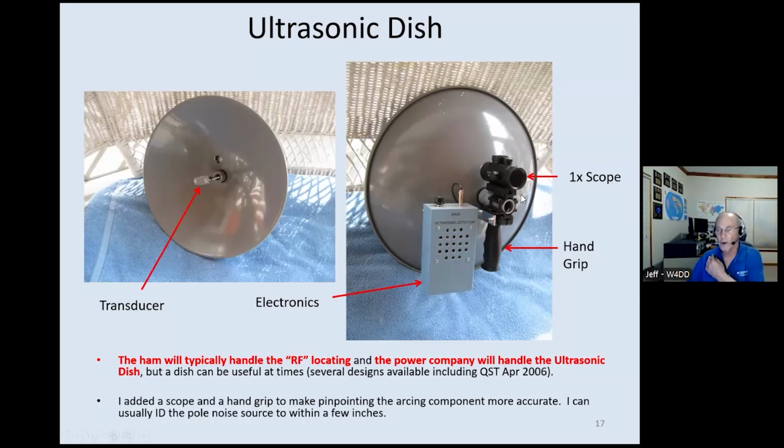I added a scope to mine after using it for a while. I wanted a more precise way to find the part on the pole, and that has really helped me a lot. I can usually resolve it within a few inches of the issue on the pole with the scope.